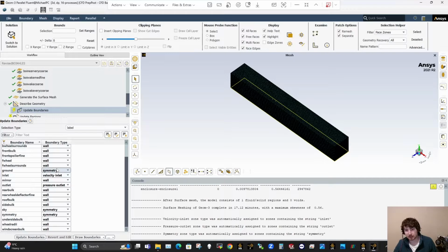It saves on the cell count because you're not going to really have growth of a boundary layer there, since the relative velocity between the free stream flow and the moving ground is the same. So you can save a nice bit of cells by not growing that on the ground. You can do it both ways. You can grow it and not grow it and compare your results, and you'll see there shouldn't be any difference.